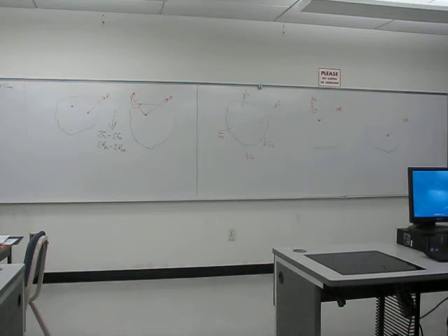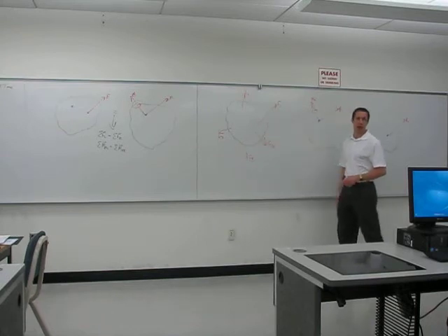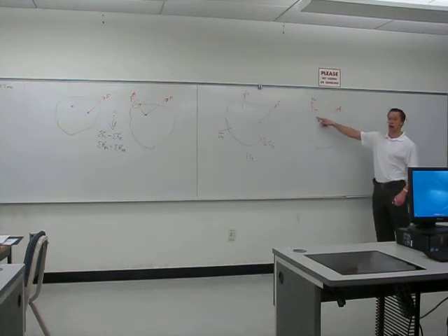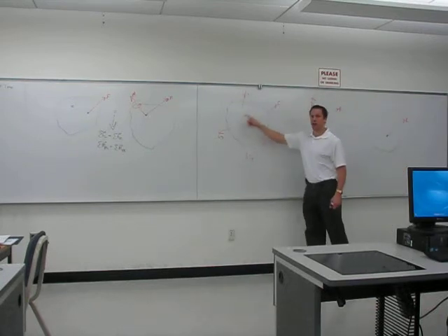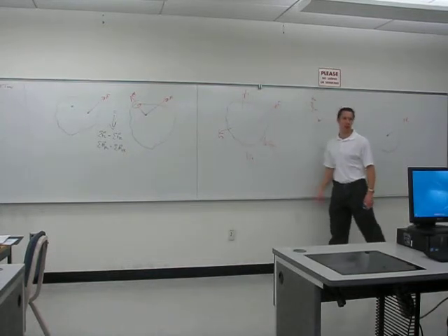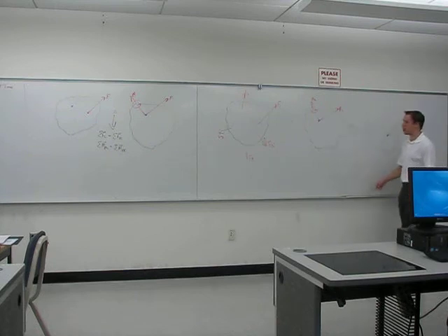So we might be shown a system of forces like we have here in the extreme left-hand picture and be asked to find an equivalent force couple system. That means a force and a moment vector at some particular point. We might be asked to just take these 5 forces and find a resultant force and the point where it should be applied, so that this one force will have the exact same effect as all of these forces, as well as this equivalent force couple system. So we could be shown the left-hand picture and be asked to find either one of these, or maybe even both of these right-hand pictures. We'll see that in the examples that we go through today.